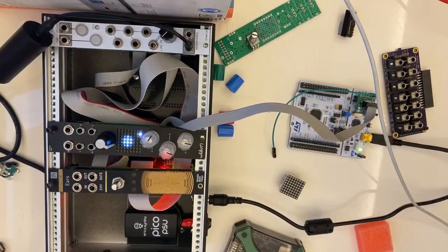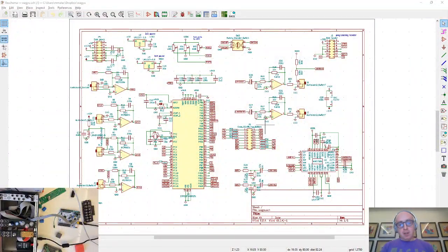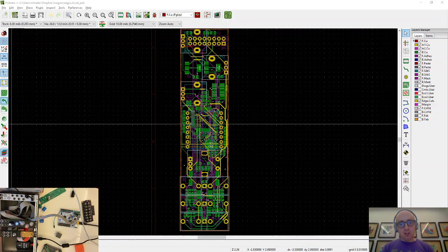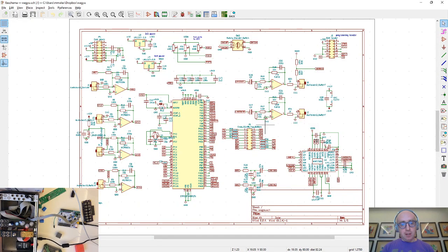And then mistake number 3, idiot. If I go back to the both cams view, I've seen the schematic. So we have the codec is configured over I2C, the I2C bus, and I didn't put any pull-ups. And you can put pull-ups in the chip, but they're too weak.